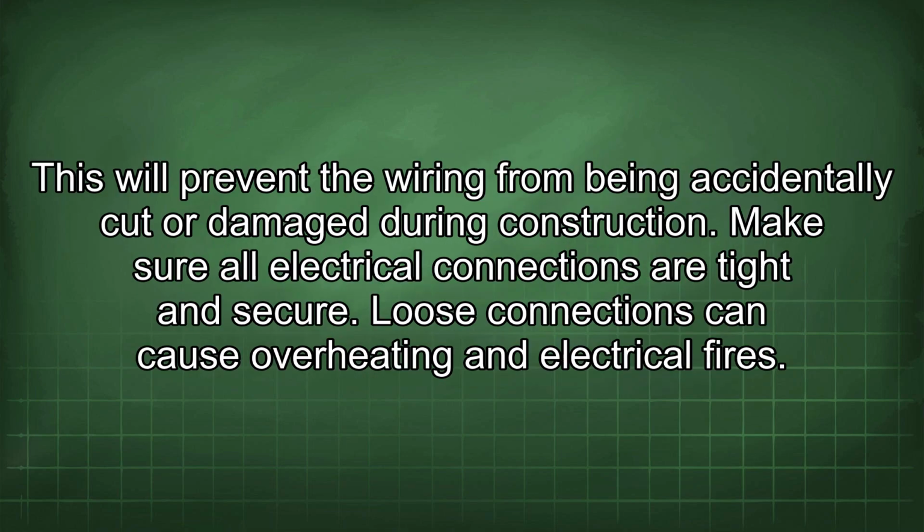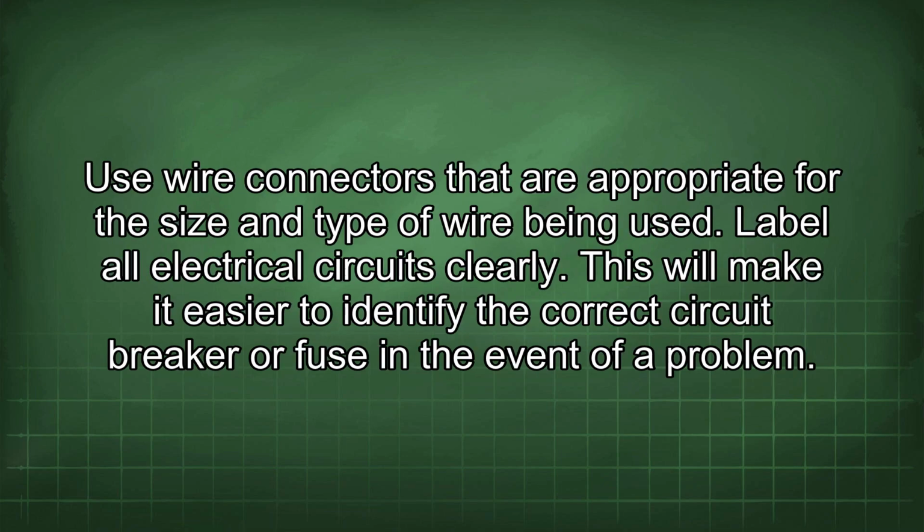This will prevent the wiring from being accidentally cut or damaged during construction. Make sure all electrical connections are tight and secure. Loose connections can cause overheating and electrical fires. Use wire connectors that are appropriate for the size and type of wire being used.